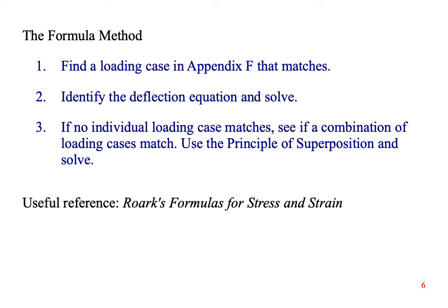The curvature method is useful for finding deflection when moment is constant, but you know from experience that M is almost never constant in most beam problems. Fortunately, engineers have worked out formulas for calculating deflection for many loading cases. You have many of these formulas in Appendix F.